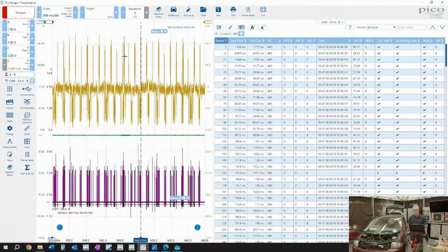So it's a great technique when it comes to actually just seeing if that ECU is online for one, because if it's online, it will be transmitting, and then we'll be able to determine from current flow. Remember, you need to be on a branch for this test. That works well. Rather than be on the trunk of the network, we're actually on a branch. If that network is going down for whatever reason, it'd be good to monitor the current to that ECU, because if that's the ECU that's responsible, you'll see a peak over and above typical CAN traffic. So it is a powerful tool.